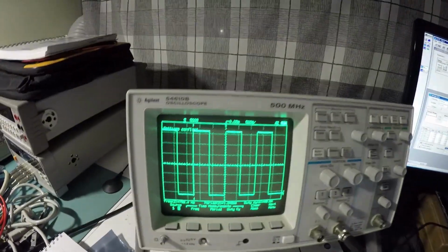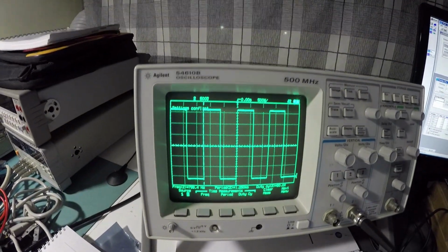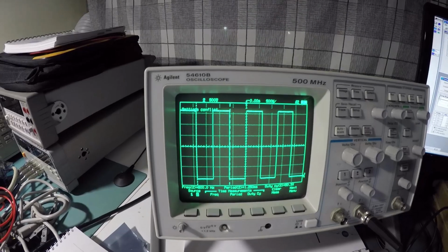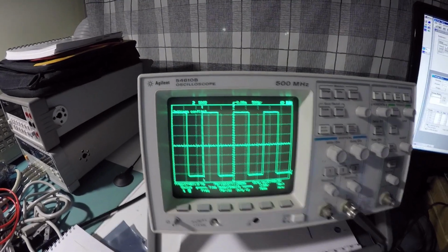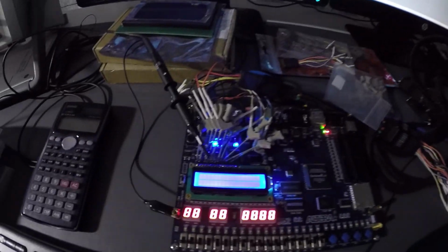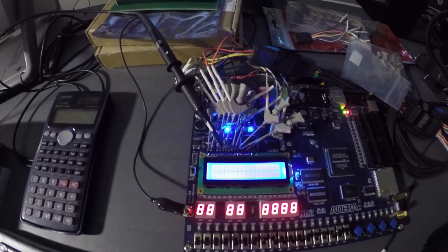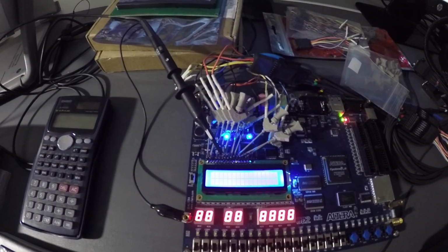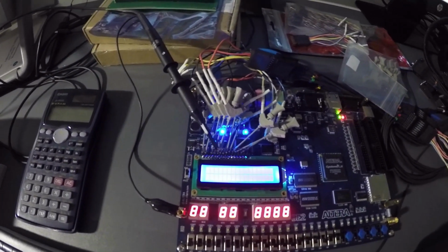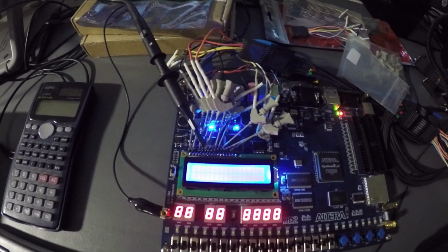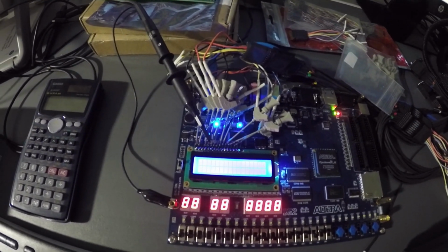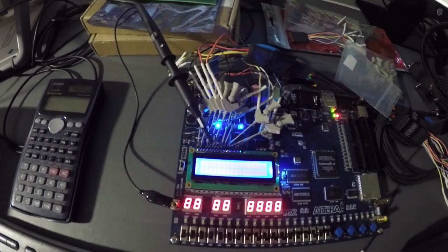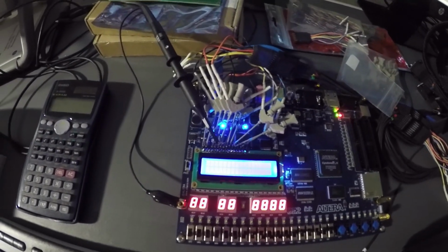Well, by using a 1600 hertz signal, chances are we're exceeding the speed of the LCD display, the maximum frequency that it can handle. So when we take a look at the data sheets, chances are that's why the signals aren't able to be grasped.